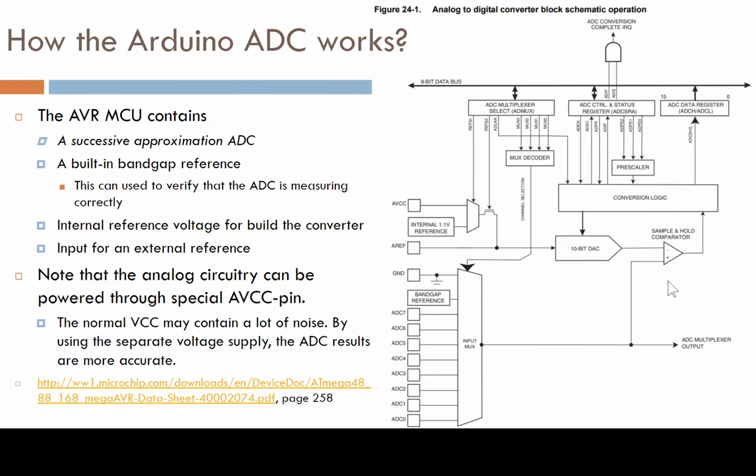Then you know that at that point you have exactly, say, 1.1 volts or something like that. Another point, you can also calibrate the A to D converter by grounding the signal, which means this should be 0. So now you have 2 points and the linear behavior of that A to D converter. So you should actually be able to calibrate things. Nice.